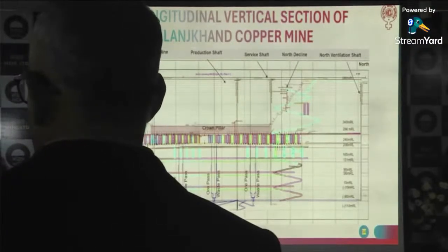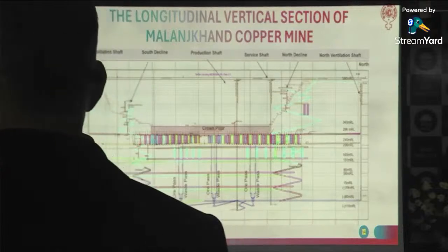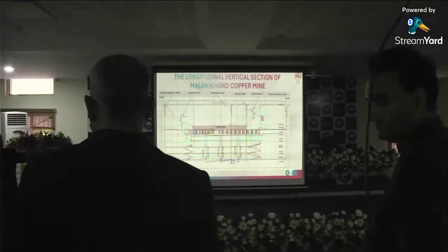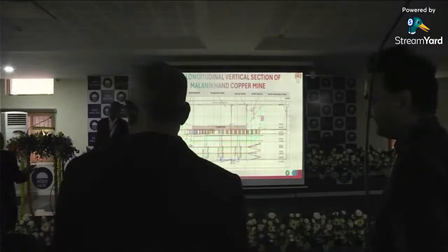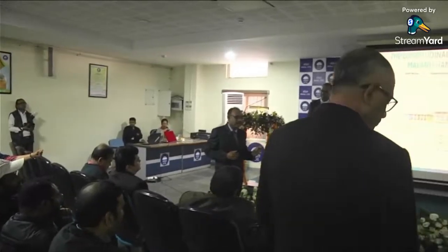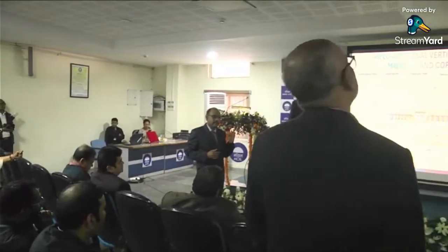They have very difficult rock mass conditions there. In their north lode, in fact, you can even push your hand through their rock. Still, they are doing mining. They are doing sublevel stoping and blast-hole stoping, all with the help of shotcrete, split sets and wire mesh. They are supporting the roadways, and now they are doing the mining. I very much recommend you visit the Rajpura Dariba mine. It's a very treacherous mine, so you should see that.